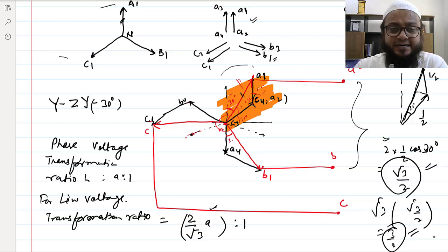So basically, I have said the star delta connection is mostly used, and the delta star combination. These 2 types of connections are basically used in the transmission line network. And even the delta star combination is used at distribution level as well, because let's say in distribution level we want a single phase supply as well. So in that case, the star will be connected toward the low voltage side.